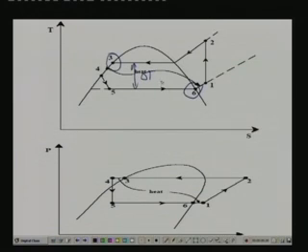That is what is shown here. This is exchanging heat like this. In this process this temperature is reducing and this temperature is increasing, and both the processes are typically almost isobaric. So subcooling takes place along the constant condenser pressure line, and superheating takes place along the constant evaporator pressure line.